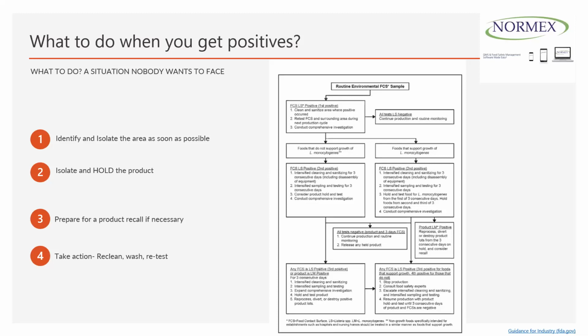But the Listeria would come back after every 8-9 months, which was concerning, and we were thinking why this was happening. So later on, we found out there was some debris that came in through the trucks that could have contributed to this issue. And so we used long hoses for loading or unloading the raw milk into the tank to rectify the issue, and nothing came back after it. So it depends upon experience, it depends upon what's happening in the facility.